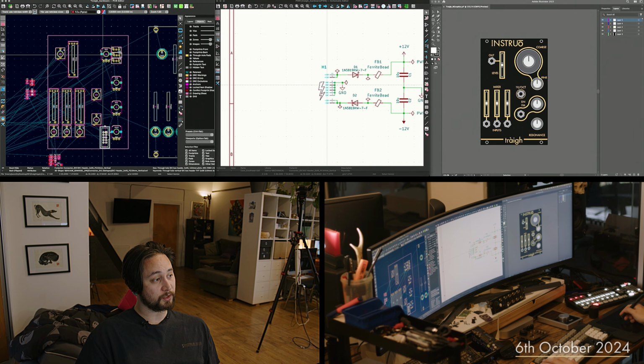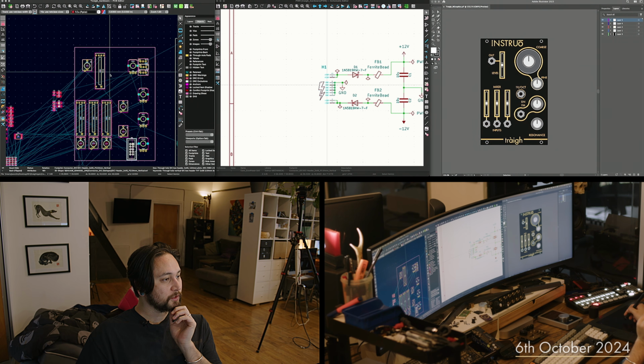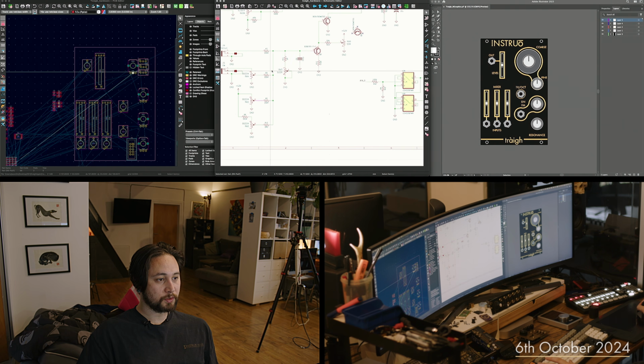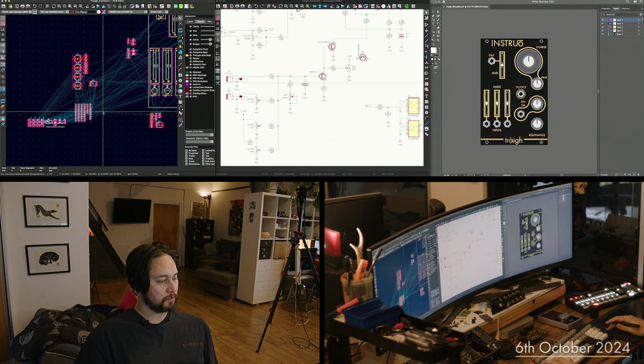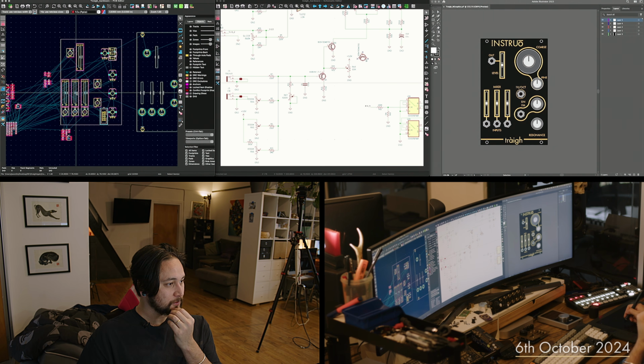So if the main filter circuit is up here, and get the transistor ladder all neatly configured. Trim pots, these actually pertain to the volt per octave input, which is this guy. So that's actually not too bad for placement, so that will be correlating to stuff around here from the input controls. Coarse, frequency, so let's view this stuff here. That's all together. Yeah, this is going to quite neatly dictate itself, I think. It's not going to be too out there a layout.